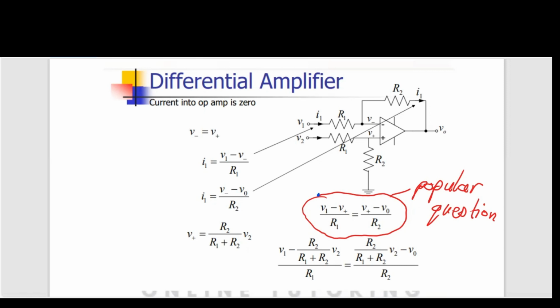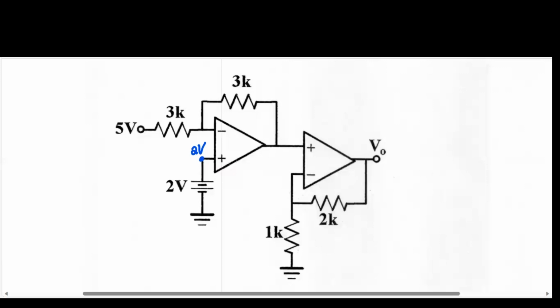They put a battery there, used as a reference voltage. Should I just remove this piece here, connect it to V plus, and then just put a battery? So it's still 2. So V plus will be 2 volts, so you're still using this equation. So if you go back to the question, in this case, this is R1, and this is R2.